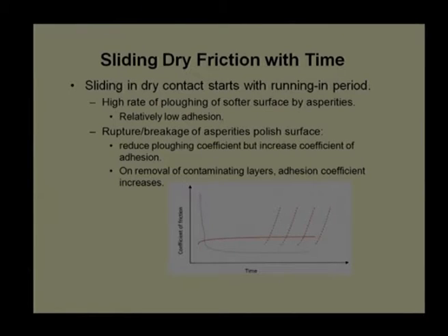That way there is a transition behavior if I try to plot it. So, the flowing effect initially I am showing going down with the rupture of asperities. After that it reaches one dynamic situation, by and large giving a constant coefficient of friction. Here, even though there is a possibility of further rupture of asperities, there is a possibility that they will remain as debris between the interface. So, two body and three body overall will come to equilibrium, and will give a steady value of coefficient of friction.